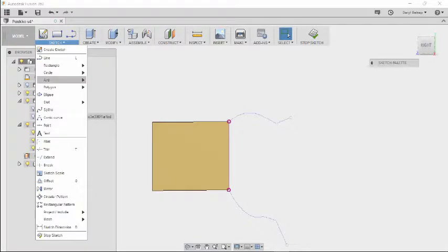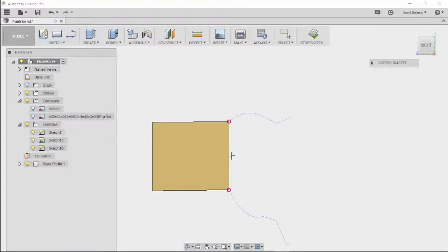I'm going to go back to the sketch. I'm going to create an ellipse. When you see that triangle, that means you're at the center of the object that you're on. So I'm at the center of this vertical line, which is where I wanted to be. Now for this ellipse to work, you start at the center, you select along the major axis, which is the longer dimension, you select that end point there, so it went up to the top of this line, creating a 20 millimeter tall ellipse along the wide surface.